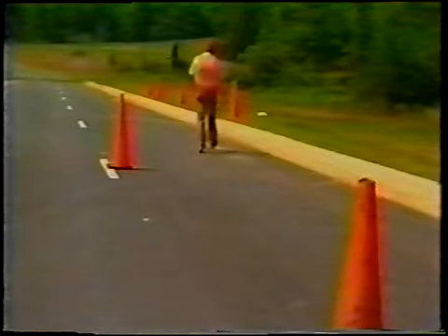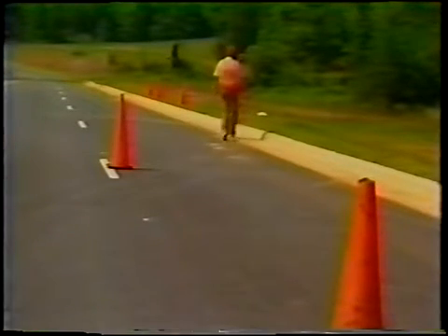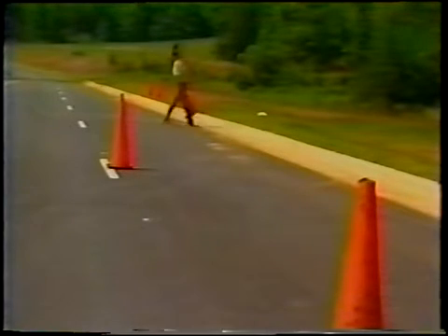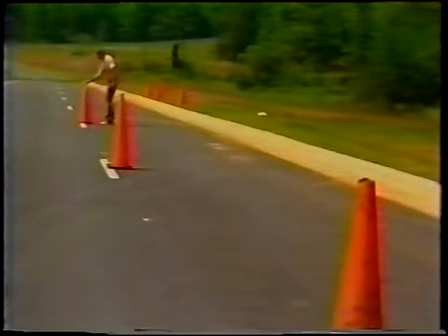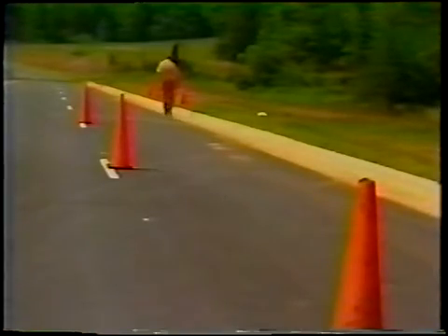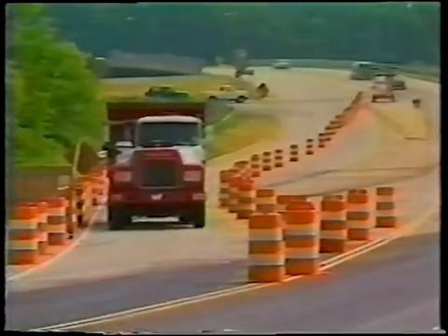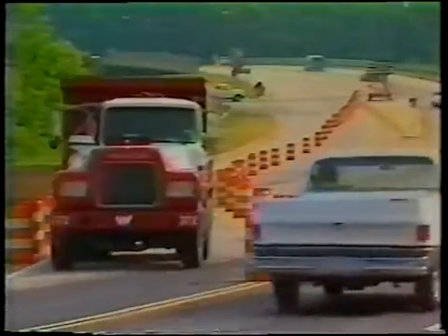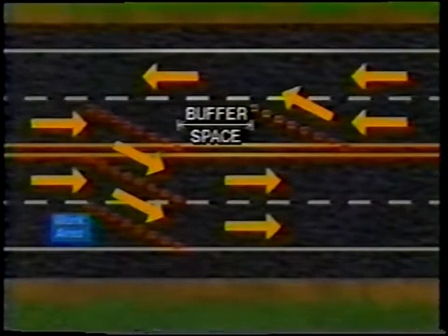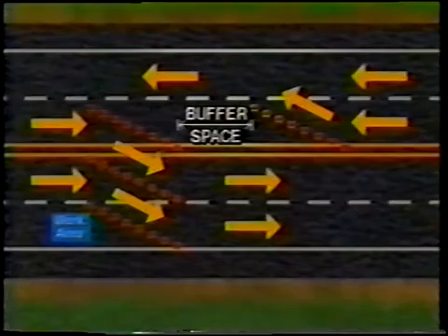When designing work zones, the following should be considered for buffer spaces. Place channelizing devices along the edge of the buffer space. The spacing should be no greater than twice the speed limit. Situations occur where one lane of traffic uses a lane that normally flows in the opposite direction. In these situations, a buffer space should be used to separate the two tapers for opposing directions of traffic to help prevent head-on collisions.